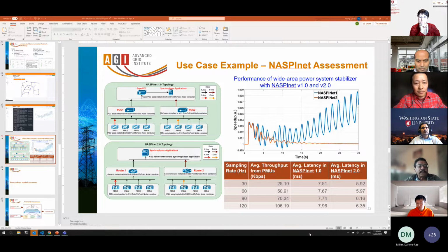That shouldn't make a difference, Henry, in a good design. If it is hundreds of milliseconds, then it's possible that it changes the response of the system. But if it's in the milliseconds or even tens of milliseconds, it should not affect it, because the swing looks like about a 1.7 second period, so around 0.6 hertz. Even if we say 30, 40 milliseconds, that's still a small portion of the swing. So in terms of degrees, that's really not very much.